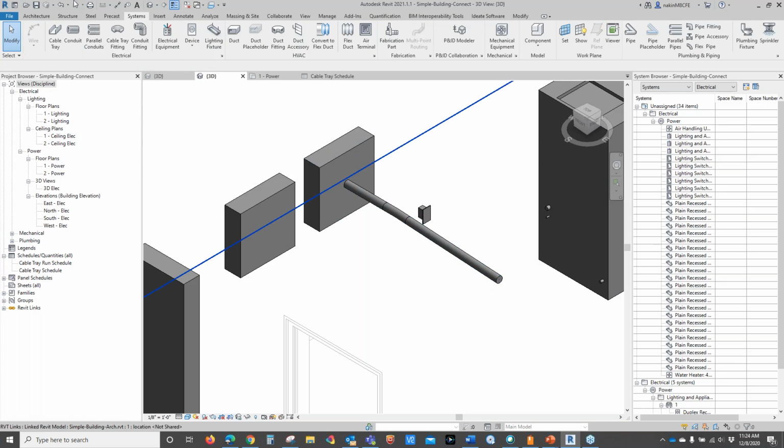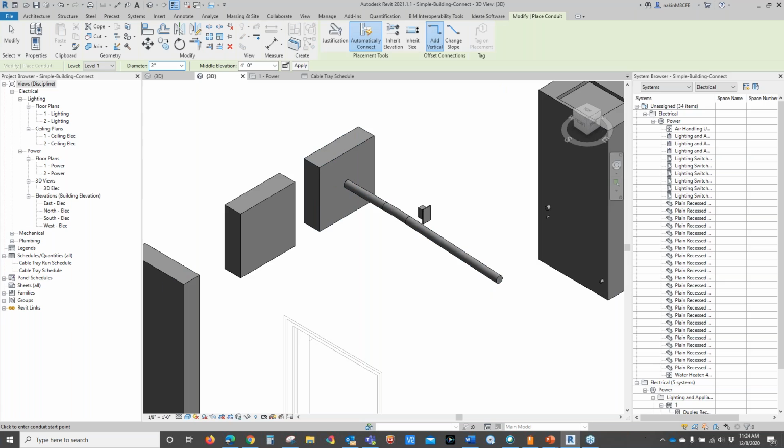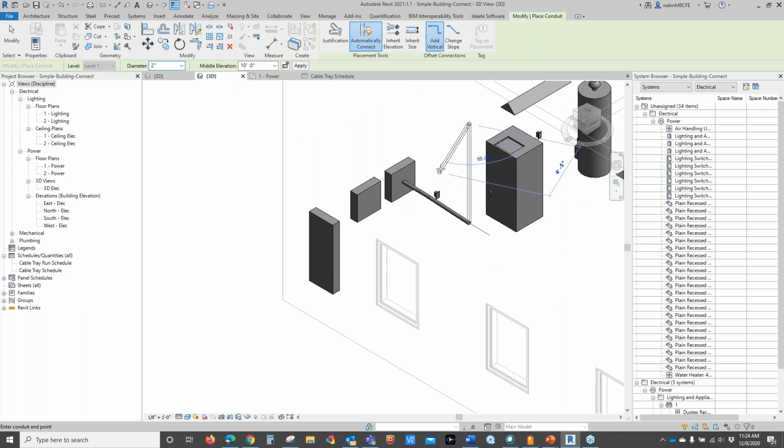At any point, if I want to take the conduit, okay, it gives me an endpoint, and I'm going to make the elevation 10 feet. Okay, so I went back to the options, made my elevation 10 feet. It draws a 10-foot stick of conduit in the top there.